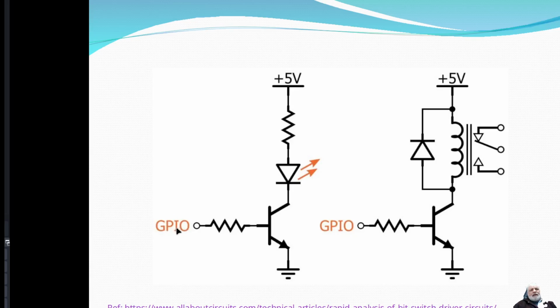When the GPIO pin goes high, to a 1, that's going to turn this transistor on and current is going to flow. So we want to make sure that this transistor hits saturation. If the transistor is in saturation, we'd be at about 0.2 volts, maybe a little bit more depending on the transistor, but usually we use 0.2 volts for saturation between the collector and emitter.